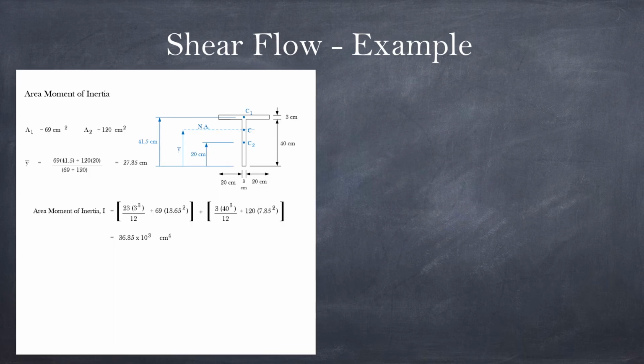So the next step is we're going to calculate the area moment of inertia. This one here, we don't know where the centroid is. Again, for the area moment of inertia, I emphasize so many times in the shear stress, we use the whole cross-section area, not the cut area. Never. In these two fields, the stress by bending moment and anything to do with the shear stress, we're going to use the total area, right? So we have to find where the centroid is, so that we can measure the distance between the centroids, and then we calculate the area moment of inertia.